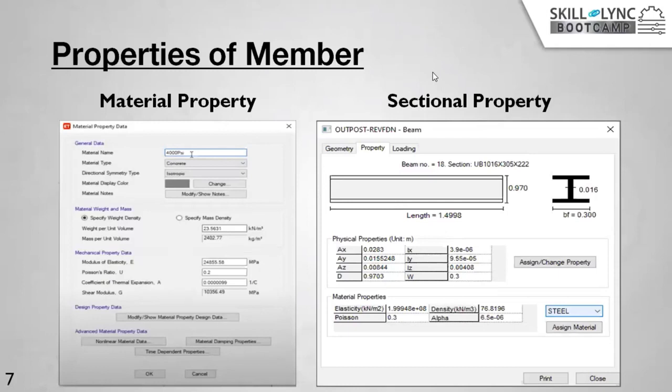So the section selection in the section property is very much important. During analysis, whatever section you choose, the result is based on that. Once you have designed, if you want to change some section property, you have to rerun it, and you have to be sure whatever provided section is analyzed and designed in the same manner.